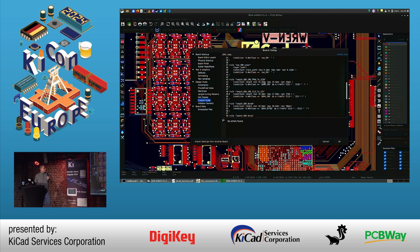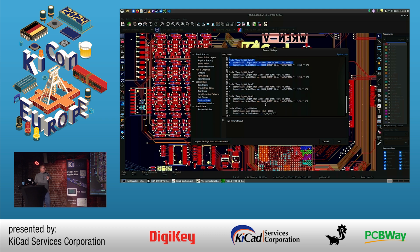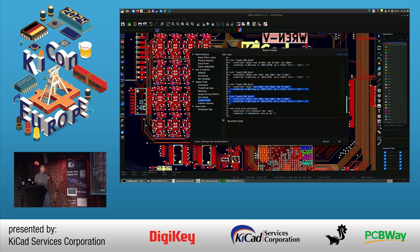There are two for the address because we have two chips, and we have four additional rules matching the lengths within each byte group. In a typical DDR4 controller, you can have a different length for the control bus, as long as the difference fits within, let's say, half of a clock cycle. And each byte group can have a different length. This greatly simplifies routing, but nonetheless, you have to align them within each group. So this is a complete set of rules for two DDR4 chips. What's next?